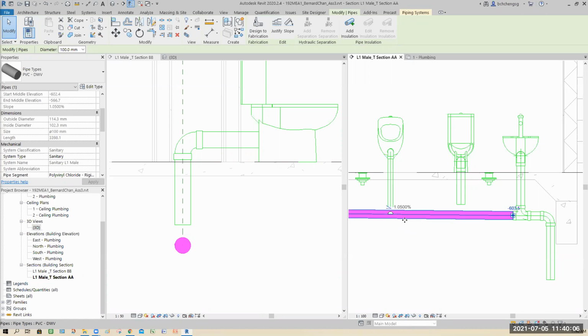So when they install, they must ensure that it's a 1.05 slope percent, at least for a smooth flow. So maintaining the position is important. If they don't maintain that properly, in 2-3 years they have to come back for maintenance. You see how often HDB pipes need maintenance in all your toilets? Very rare, right? Because installation is important.